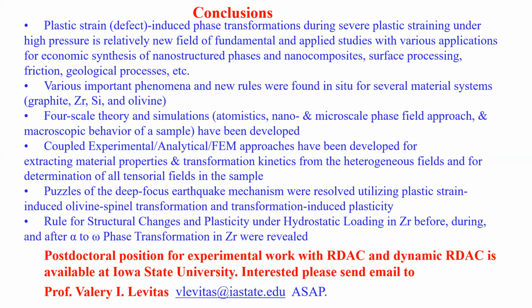Does this concept of energy result in what we call the steady state? No, steady state is not related to energy. It's a steady state in dissipation. This is more like the theory by Prigogine, the theory of steady-state behavior of strongly nonlinear, non-equilibrium systems, because this is what happens under severe plastic deformation. Energy stays steady, but this is not important. What is important is that the microstructure remains steady, yield strength remains steady, and the minimum pressure for phase transition does not change anymore. I would not connect this to energy. It's more a theory of dissipative systems than something driven by energy.